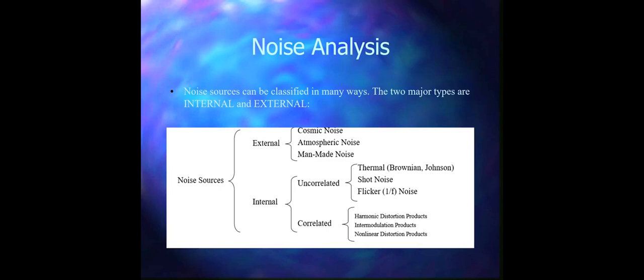So basically what happens is the charges rapidly and randomly speed up and slow down, or in other words, the current in the system fluctuates above and below the average value that would be predicted by Ohm's law. The rapid current fluctuation produces an AC noise voltage, and that is called your Johnson noise.